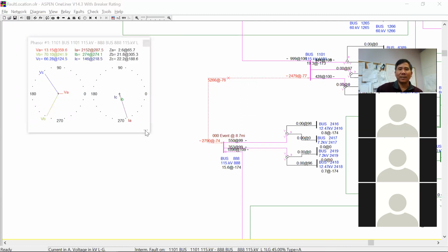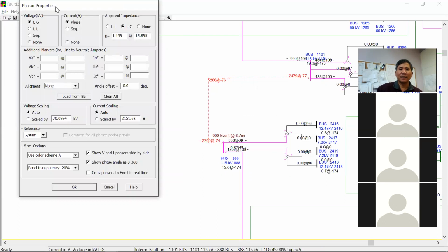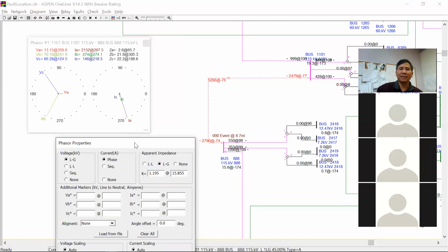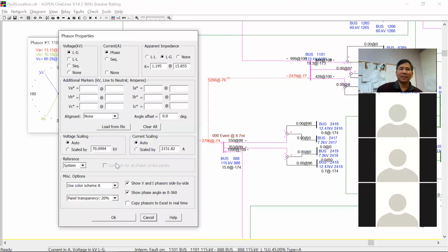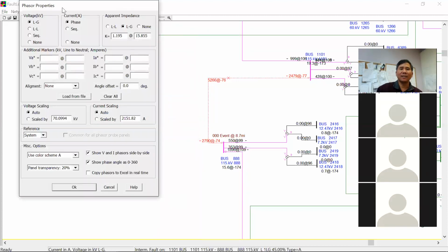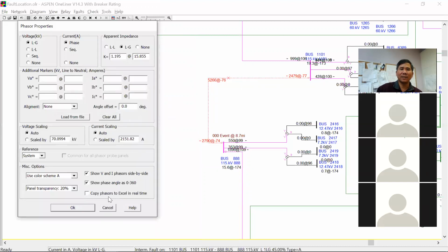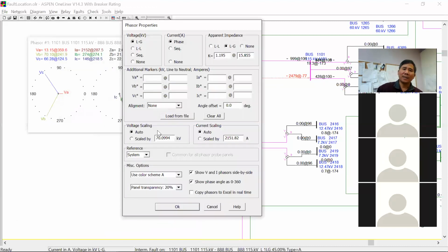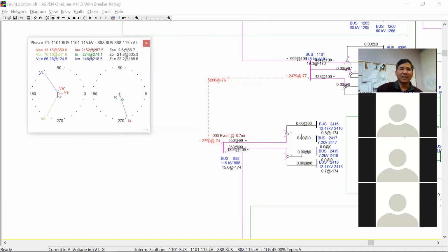And to get all the options that you can change in the phasor, you click on this button down here, or you can also simply double click on it. So the content of the phasor is exactly the same as before, but for the new one, you have many new options. For example, right on this phasor, you can specify additional markers that you can put up here so that you can compare with. So if I say 11 here at the 90°, then you see this 11 and 90 show up here.